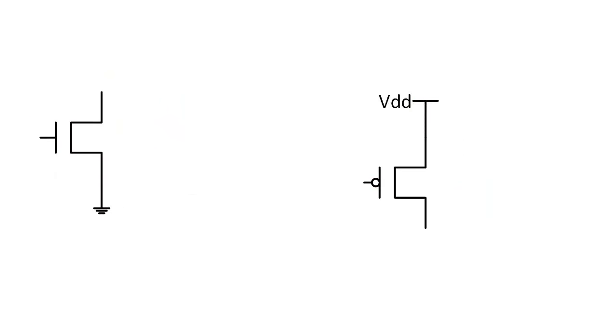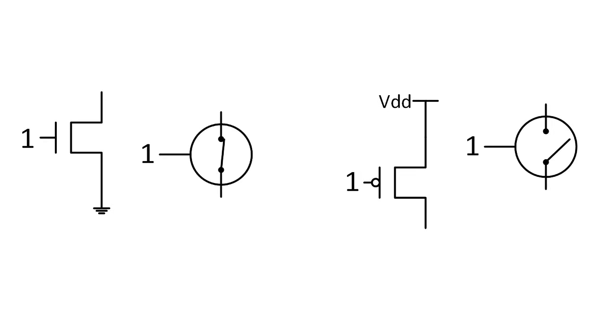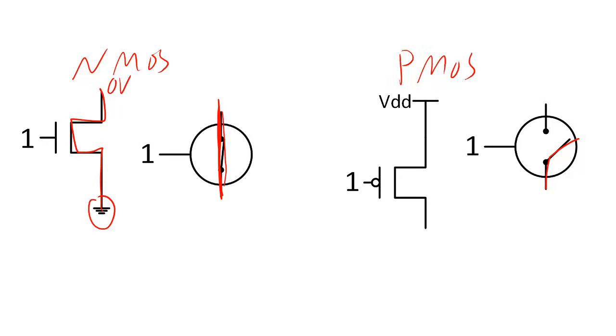And so how do we actually make these work, and what do these actually do? Basically a transistor is an electrically controlled switch. If we put a 1 in, or a high voltage, the NMOS becomes a closed circuit, whereas the PMOS becomes an open circuit. Let's explore this a second longer. When this is closed or shorted, there's a direct path from ground up to here. So basically our output terminal has a 0 volt output. Whereas this guy, since there's an open circuit, has no current going through it, and so this is basically a dangling wire. It's not connected to anything.